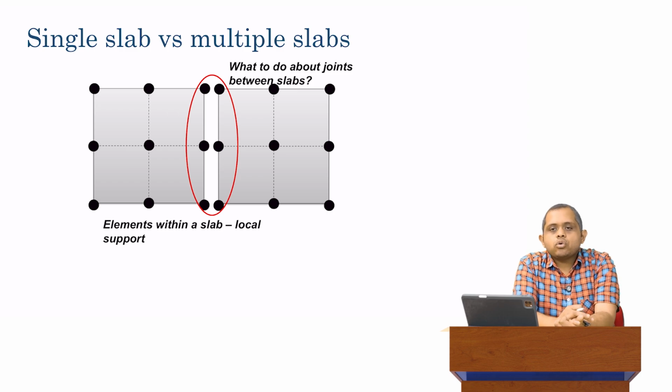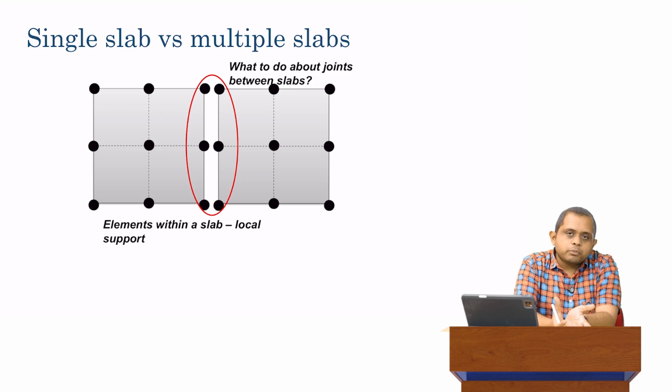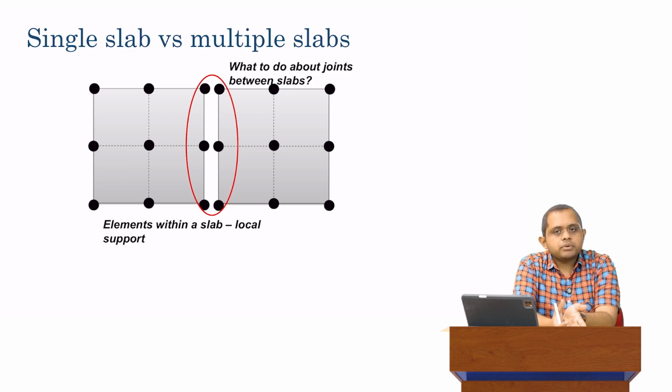All right. So all our discussion so far was basically for one slab. We discussed that we can do a 1 element approximation to a slab, a 4 element approximation, a 16 element approximation, etc. All that was one slab. But obviously, a JPCP section is not one slab. JPCP consists of many slabs. And so now because you have so many different slabs, how do we analyze the fact that we have multiple slabs?